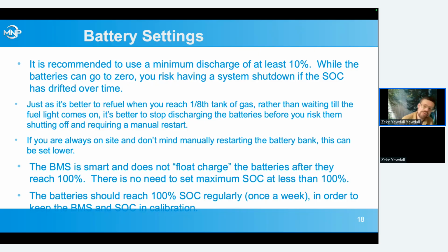We're working on improved firmware for the batteries, which will do that recalibration at state of charges other than 100%. So if you have a really slow discharge, it'll actually recalibrate and say, I'm not at 100% anymore, even though I didn't see any current leaving. I'm seeing my voltage go down, so I'm going to recalibrate. But for now, this is a kind of endemic issue to all lithium batteries currently. There is this issue with very low loads can cause state of charge drift.